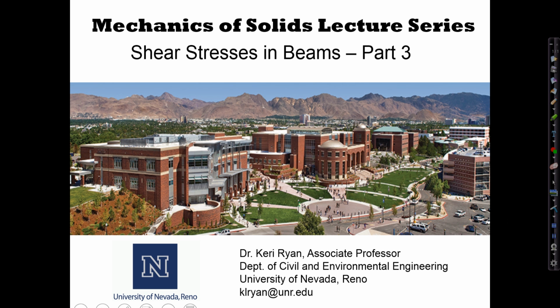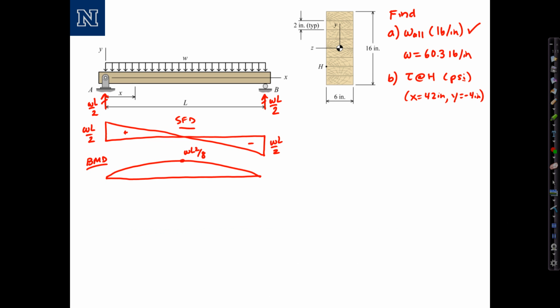In this series of videos, we're looking at examples to compute shear stresses in beams. The next example is a continuation from the previous video. In the first part of the video, we found the allowable load for a maximum shear stress of 130 psi anywhere along the beam, and this was computed to be W equals 60.3 pounds per inch.